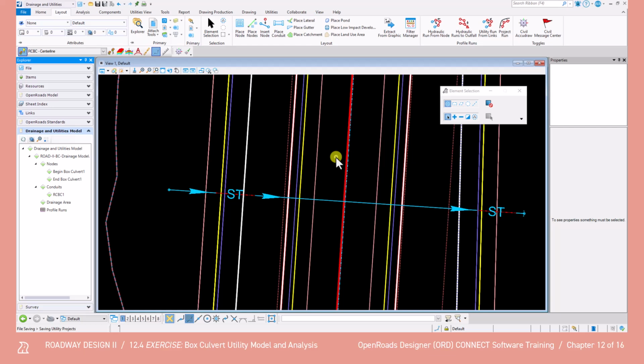The design storm flow and the contributing drainage area for the current crossing have been obtained from the USGS StreamStats. For reference, the contributing drainage area and the Q100 in cubic feet per second are provided in the figure in the manual for step 15. From this data, we can determine that the box culvert will need to accommodate 464 cubic feet per second without overtopping the roadway to meet the 100-year flood.